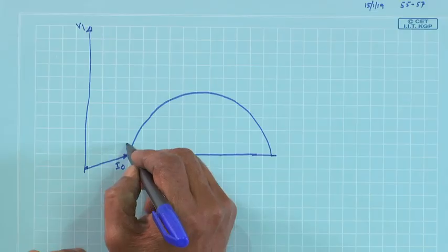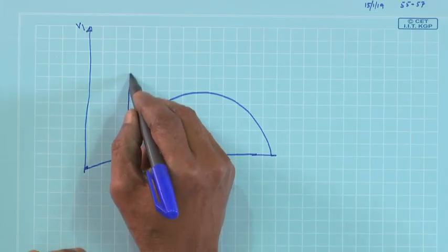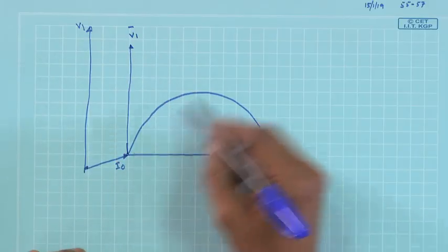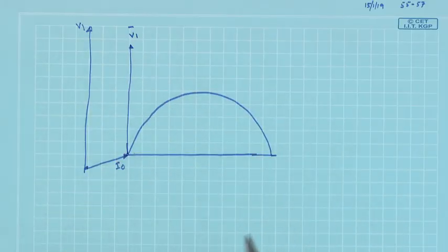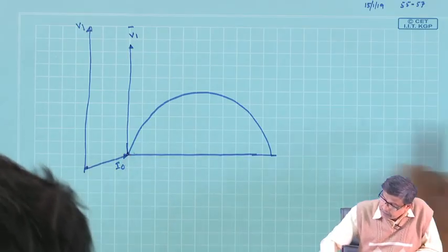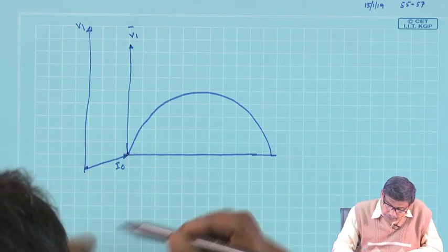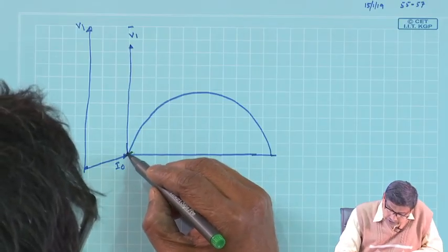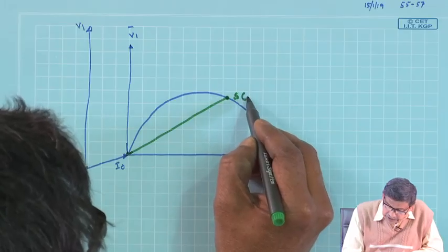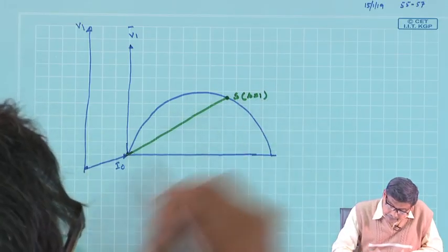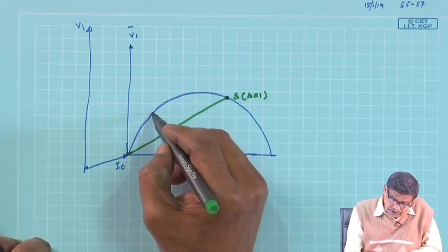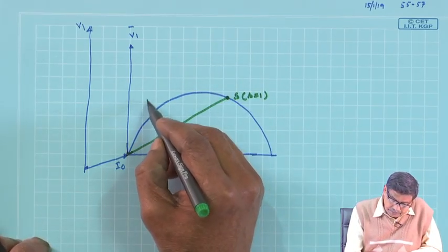Similarly, here, if you draw a line parallel to this, that also is V1. So, this current is that I2 dashed reflected current, and at S equal to 1 it was like this. There were two operating points we considered. One is at S equal to 1, which means at standstill condition, and another is the actual operating point, which could be lying here, P.